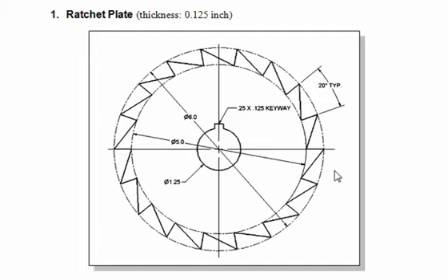At first glance, we might be thinking of the many lines in the design we need to create. But if we realize the outer edges of the design are symmetrical about the center, we can start by drawing only 2 lines and complete the design by making copies, rotating about the center of the design. In AutoCAD, several commands are available to create duplicates, such as the copy command and the rotate command. These commands will also allow us to create copies one at a time.